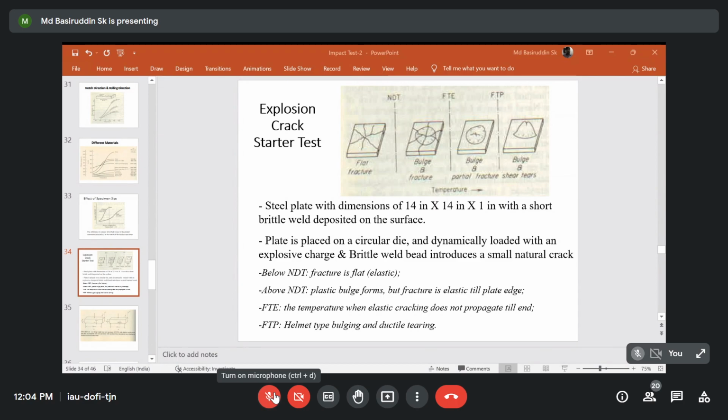So basically we need to prepare some solutions, like we use liquid nitrogen, we use methyl alcohol or ethyl alcohol, and then we prepare some solution such that we can maintain the low temperature till minus 196 degrees centigrade. Okay, and then we immerse the samples, we hold the sample in this particular solution for a certain period of time, at least 5 minutes to 10 minutes, such that the temperatures of the samples and the solution will equilibrate.